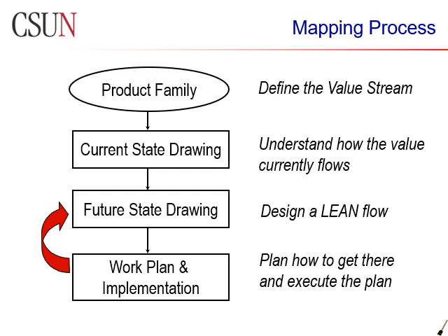So instead of drawing a value stream map for each product within the split units, we can have one for all the products that are providing split air conditioning, because they are very similar. So the first step is to classify the products. Instead of having a large number of products here, we say that these are equivalent to this small number of groups. So we need to draw one for each one of these groups. Each group is represented by one chart.